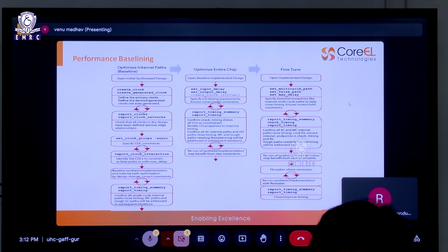So you can do it, or you can create an XDC file, a design constraint file, where you are adding these constraints. Most of these are constraints, except for the reports we are getting out. Everything else is a constraint that I am adding. You can run those constraints in the terminal, in the TCL console, and once you save your design, they go back into a single file, which is an XDC, similar to how we have done timing.